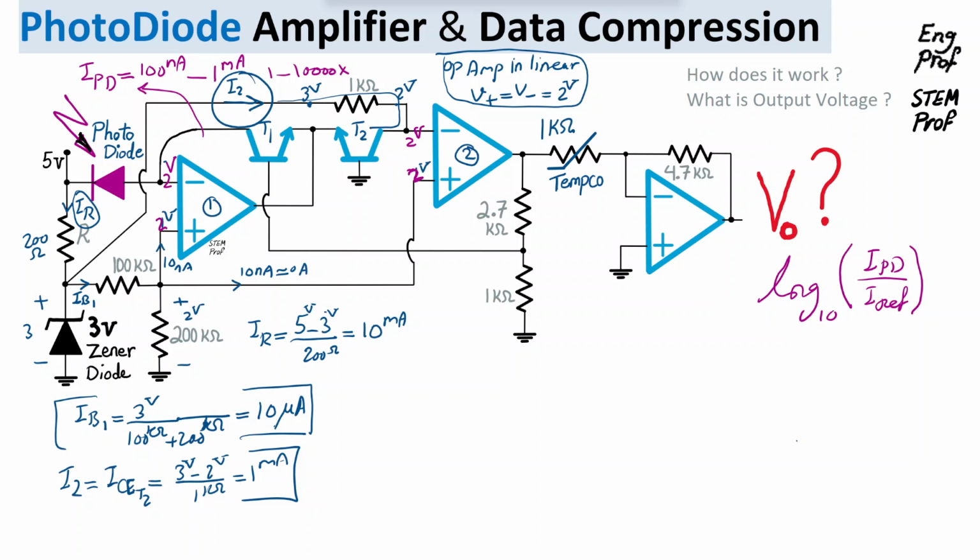All right, so this is effectively our reference current in this circuit. Via a Zener diode and the voltage divider from the Zener diode, we establish a reference current in the circuit. Now, what's going to happen for the connection of transistors T1 and T2, which are paired transistors? By paired transistors, I mean these are on the same substrate, very close to each other inside the package, and they benefit from the same junction and thermal properties.